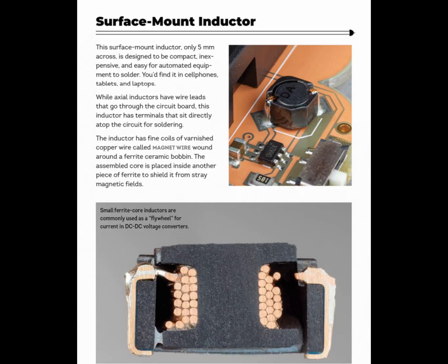For using it, check the maximum current rating to prevent saturation and overheating. Ensure the selected value fits the specific application needs. A lower DCR is desirable to minimize power losses. Verify that the inductor operates within the specified temperature range for reliability.